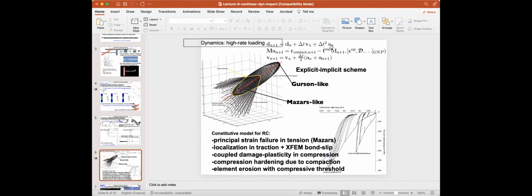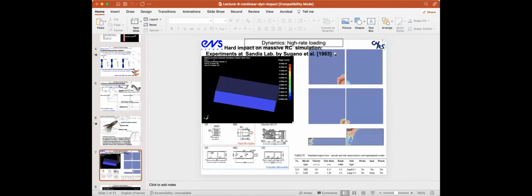Contrary to the damping phenomenon we were doing in the implicit computation, where we took linear hardening and linear softening, here you can make it as nonlinear as you want, because with the explicit scheme, you always give the displacement, and you know it's the best defined value of displacement. All the rest is just the evolution equations of these internal variables, which can be made to converge without any problem. And basically you have a behavior of your structure.